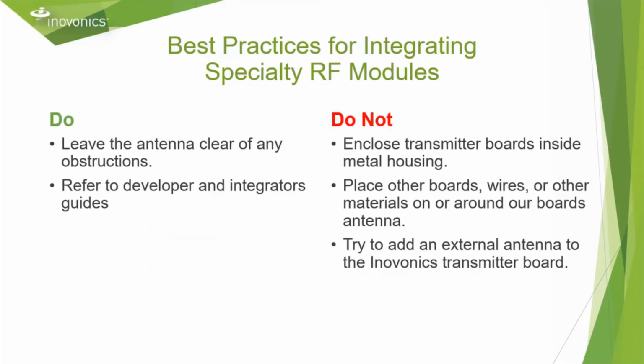When it comes to best practices for integrating specialty RF modules, always leave the antenna clear of any obstructions and refer to developer and integrators guides. It's important to not enclose transmitter boards inside metal housing, place other boards, wires, or other materials on or around our board's antenna, or try to add any external antenna to the Inovonics transmitter board.